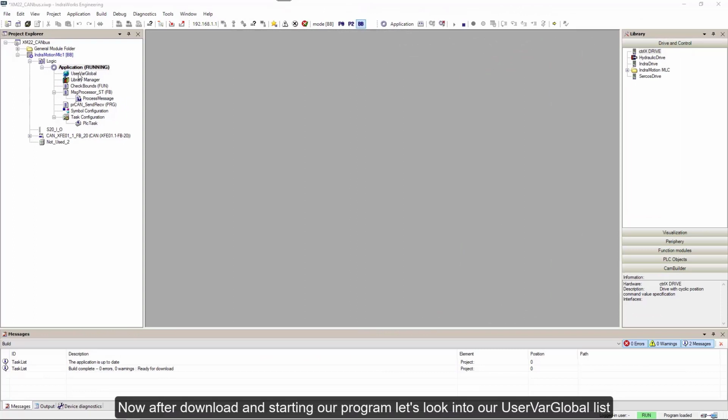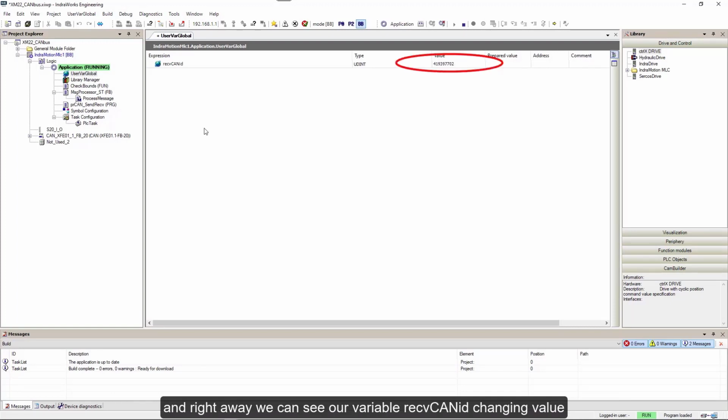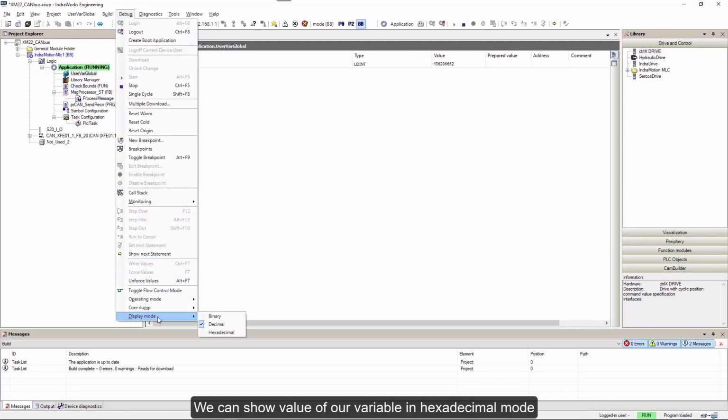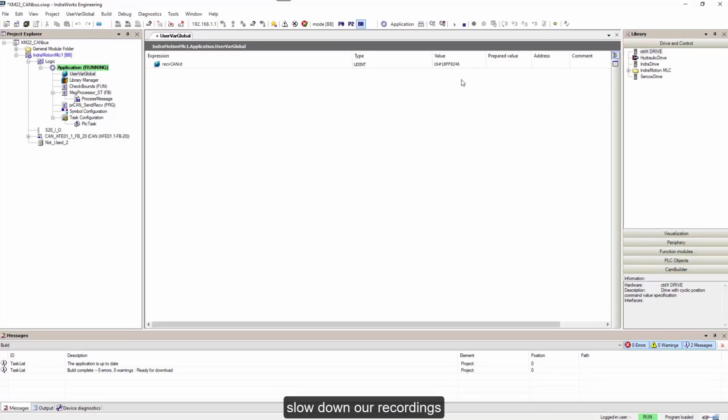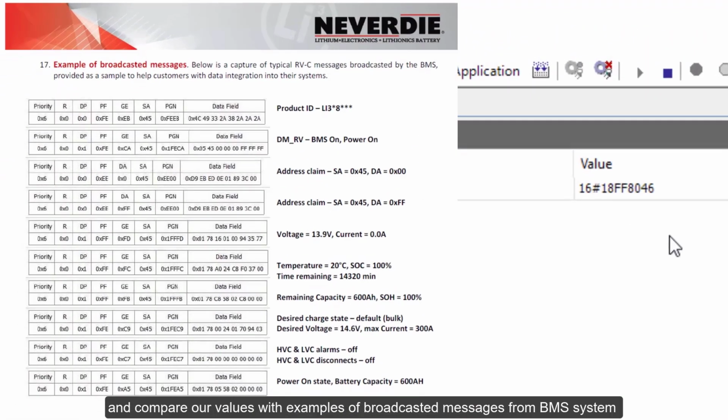Now, after download and starting our program, let's look into our user variable global list, and right away we can see our variable receiveCanID changing value. That means we are receiving cyclic messages and reading their identifiers. We can show the value of our variable in hexadecimal mode, slow down our recordings, and compare our values with examples of broadcasted messages from the BMS system.